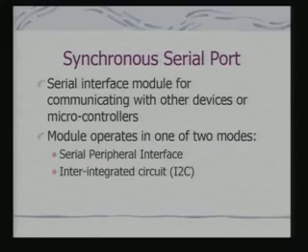There is another module which is called the synchronous serial port module. Now, what is this? This module is primarily targeted for SPI. In fact, this can be used for setting up your SPI as well as I2C, integrated circuit interfaces.